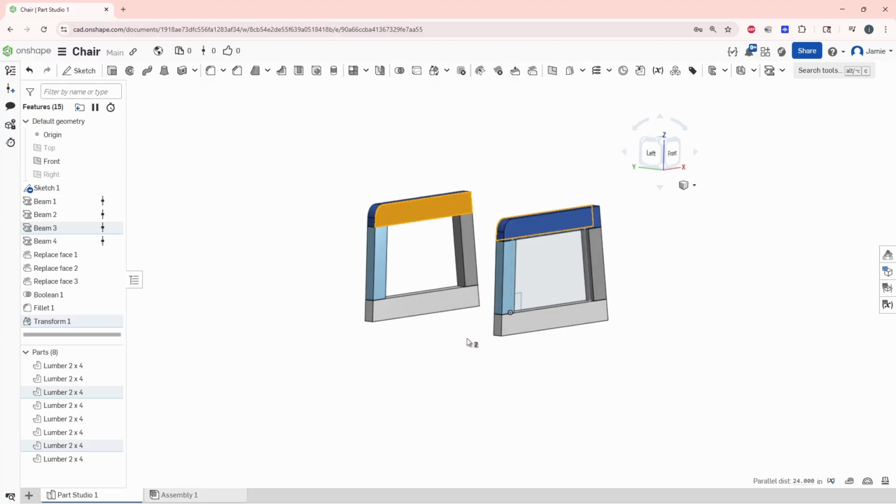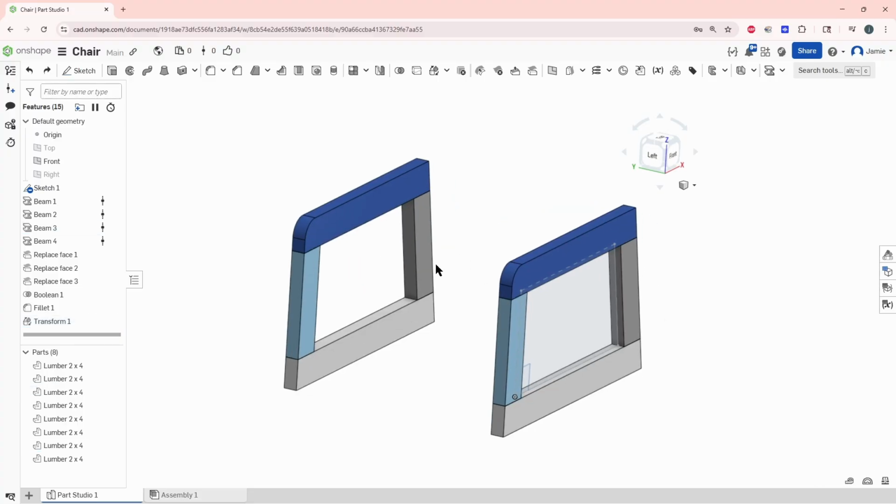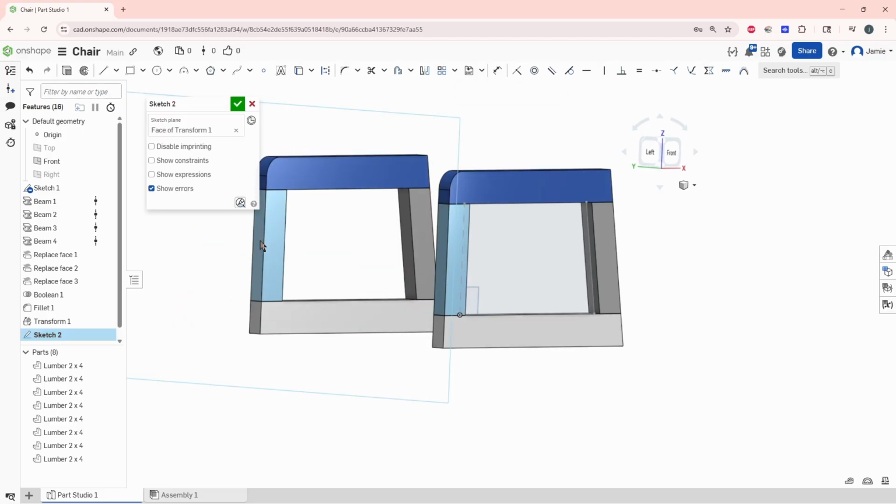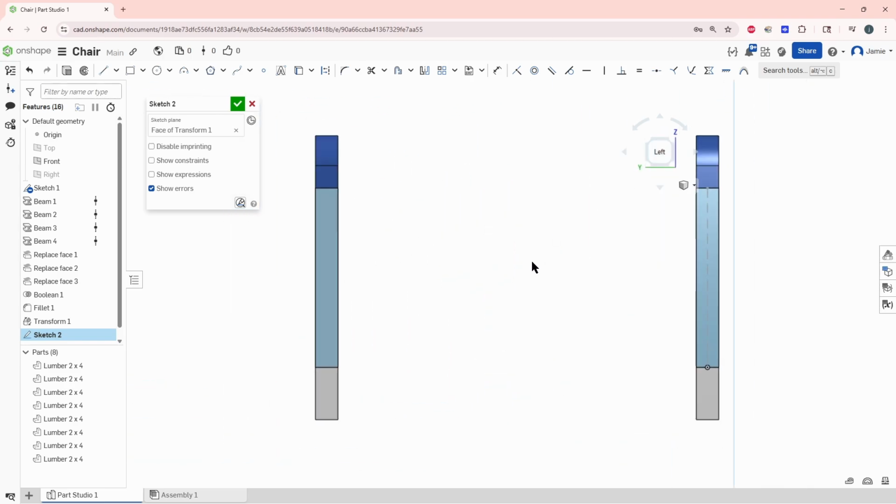We're going to build our seating platform where we're going to sit. So spacebar to get out, unselect that guy. So now we got both arms on the chair. Now we're going to create a line that goes across from this face to this face. Okay, so we want it on the flat face, which is this one right here. So we're going to go with sketch on that face right there. We're going to normalize this to left.